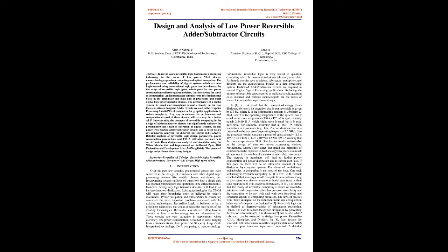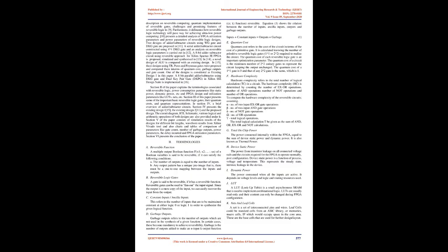Incorporating the concepts of reversible computing in the design of adder/subtractor circuits can significantly enhance the performance and speed of operation of digital systems. In this paper, two existing adder/subtractor designs and a novel design are compared and analyzed for different bit lengths, 8, 16, 32, 64. Detailed analysis of reversible logic design parameters, power consumption parameters, and FPGA utilization parameters is carried out.